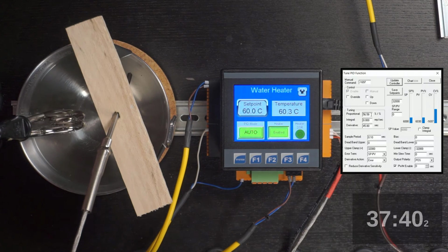In other words, from a CV calculation of 100%, how close to the set point do I want to be before that CV calculation drops below 100%? By the calculation I've made, if I have a proportional value of 64, then I'm going to keep that CV calculation at 100% up until 5 degrees before I get there. So